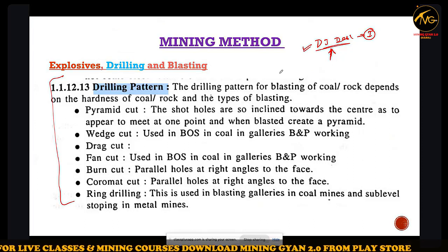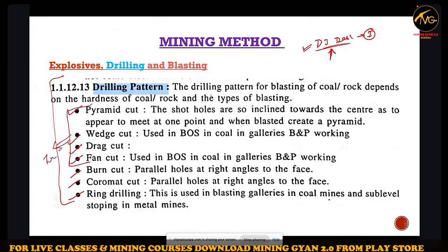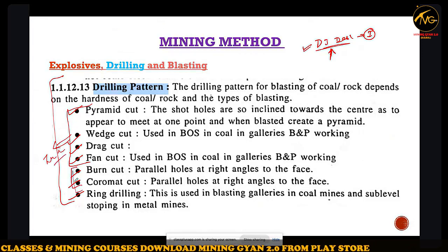Drilling patterns are of various types like pyramid cut, wedge cut, drag cut, fan cut, burn cut, coromant cut, or ring drilling. What he has mentioned is that pyramid, wedge, drag, fan use inclined drilling. Burn and coromant use parallel holes.